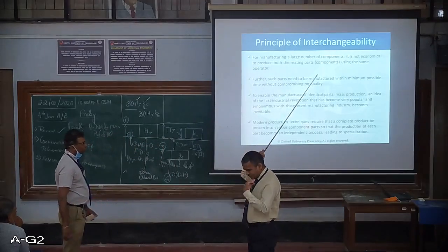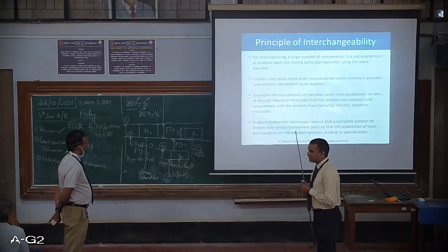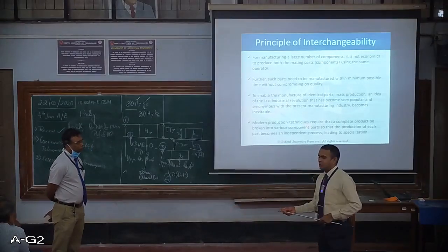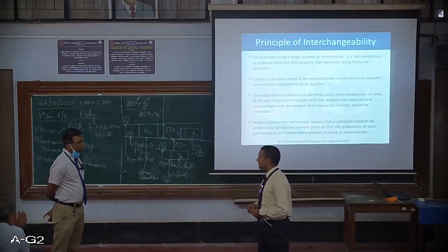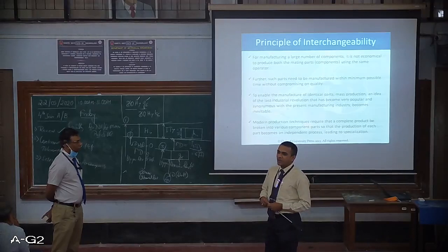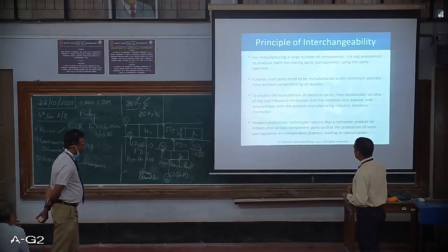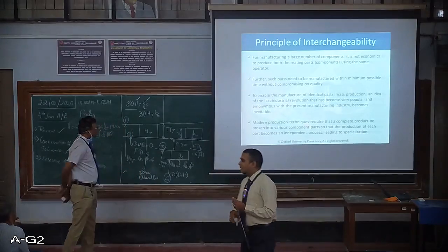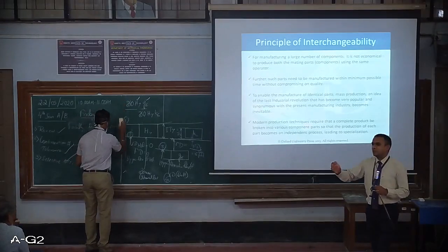So what do you mean by interchangeability? A very simple example that I can quote is this: whenever the ink gets over in your pen, you just say the name and the model, the type of pen that you have, and the shopkeeper replaces it with a different refill. Immediately you can replace the empty refill with a newer refill, and this concept can be called interchangeability. So basically, interchangeability means there will be some deviation, but that is permitted. And if you want to replace a particular product with a new product, that should be within that particular tolerance.